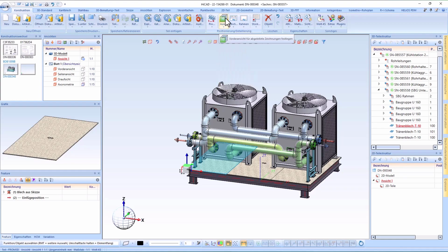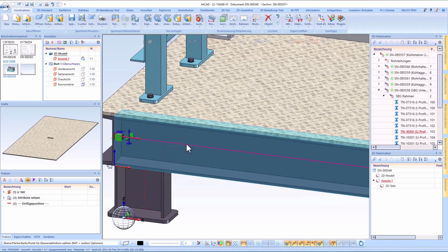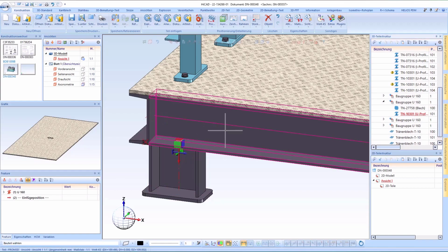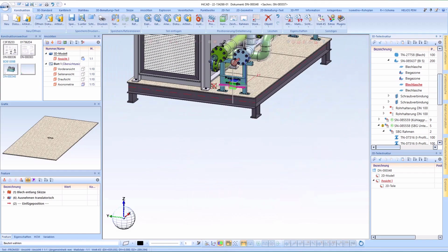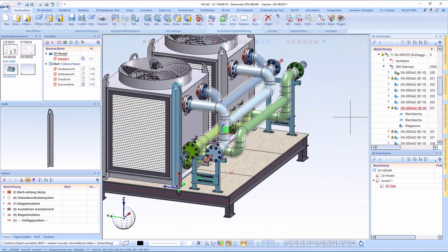After calling up the function, a part is always asked for first. After the selection, the plane for defining the orientation is queried. This continues until you end the function. The part will be activated. This way you can see the orientation of the part up to now and can react accordingly. In addition, you do not have to set the orientation for the identical parts again.